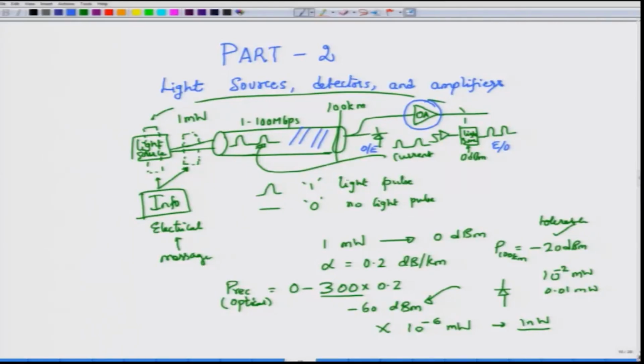And of course, we do not really have to do that, because luckily around the mid 1980s people discovered or invented the optical amplifier, so that you would never have to convert the optical signals back into electrical domain and again convert from electrical domain to optical signals. And the prominent optical amplifier which was studied first and then brought into market is called the erbium doped fiber amplifier. Okay.